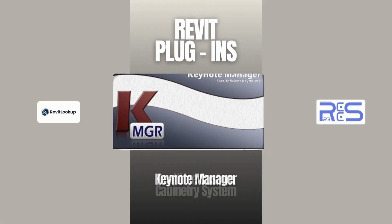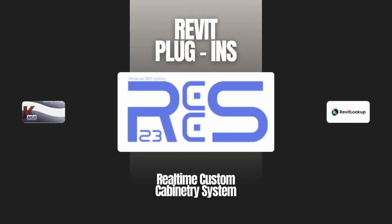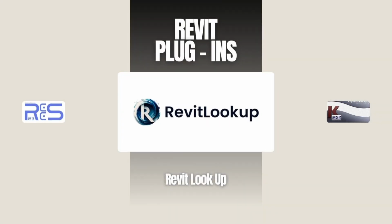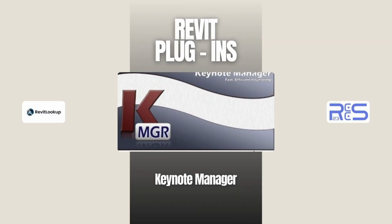Install plugins like RCCS for automatic cabinetry, or you can also use Revit Lookup to quickly inspect and troubleshoot elements. Try Keynote Manager to keep your annotations consistent across the entire model. A few of the right plugins can easily save hours every week, but before you can even open a new project, let's make sure your setup is solid.